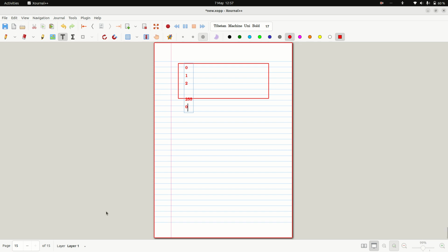Initially LED 1 is equals to 1. When control goes to the ISR, LED toggles. Naught of 1 is how much? 0. After certain duration again same thing happens, toggling, then 1. So it takes 51.2 microsecond time, isn't it?